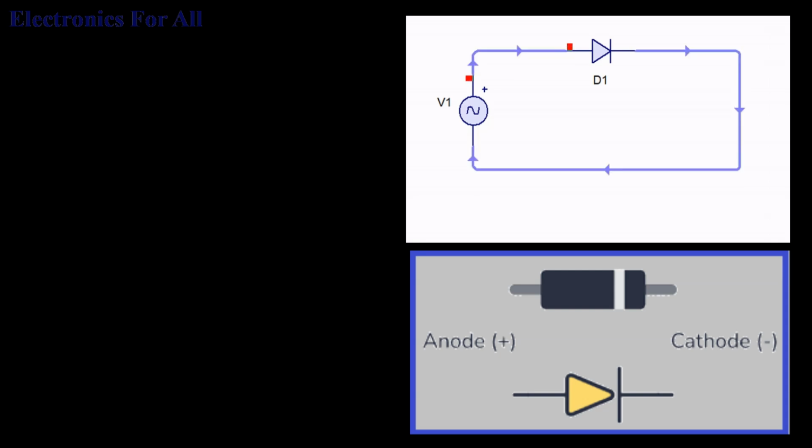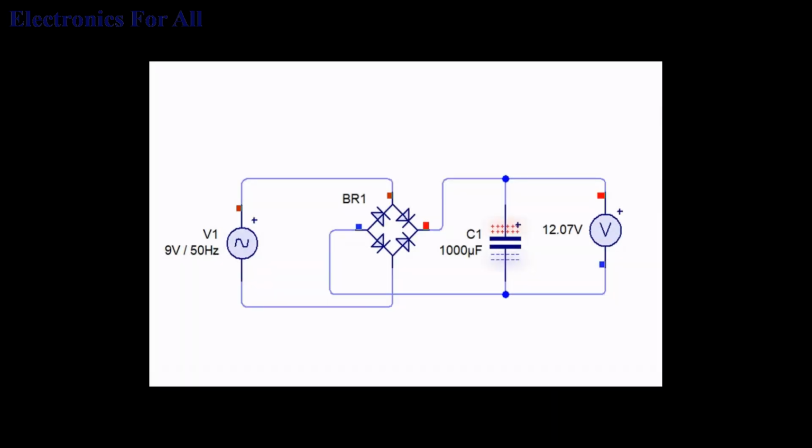Diode operation. A diode starts its operations when a voltage signal applies across its terminals. A DC volt is applied so that the diode starts its operation in a circuit, and this is known as biasing. A diode is similar to a switch, which is one way. Hence it can be either in conduction mode or non-conduction mode. The on mode of the diode is attained by forward biasing, which simply means that higher or positive potential is applied on the anode and negative or lower potential is applied on the cathode of a diode.